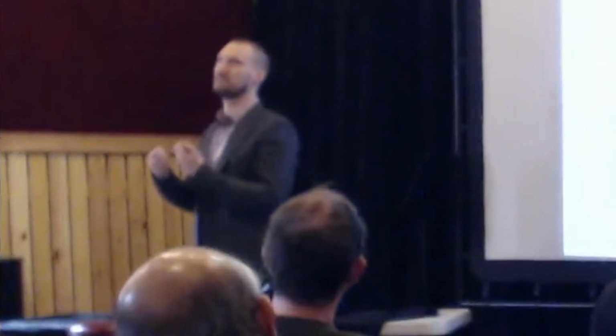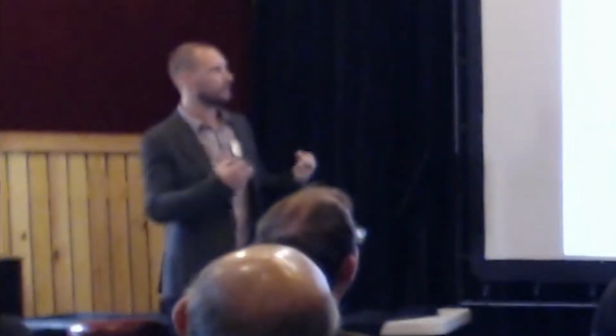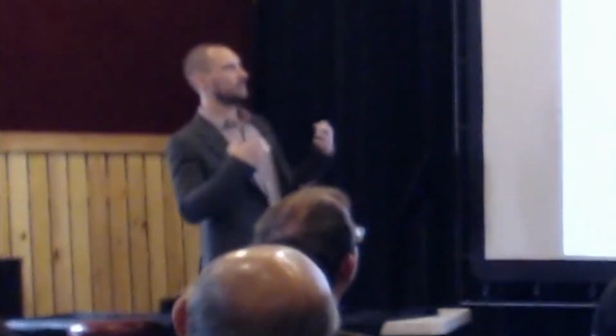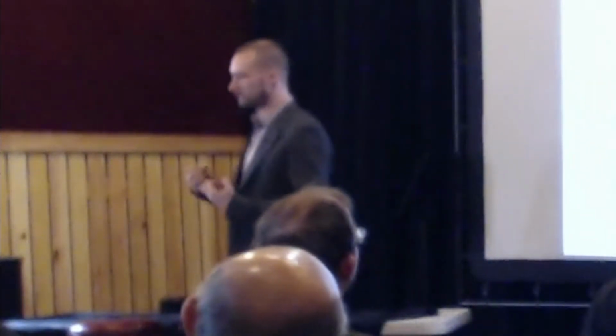The coils in the transformer itself create parasitic capacitances, which will create a low-pass filter because we have then capacitance to ground. So the transformer in its windings has the intended inductance, which creates the current's magnetic field in the core and transfers our signal from one coil to the next.